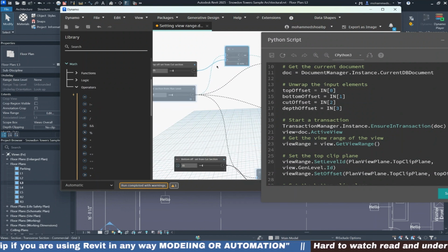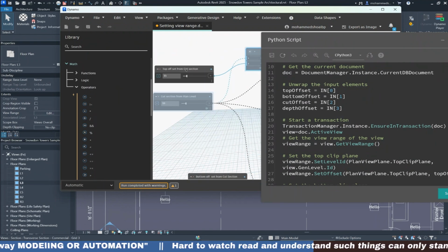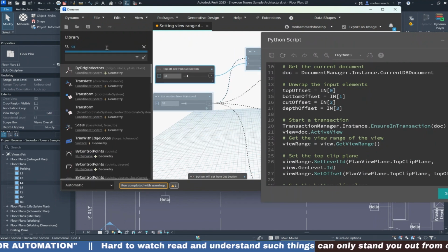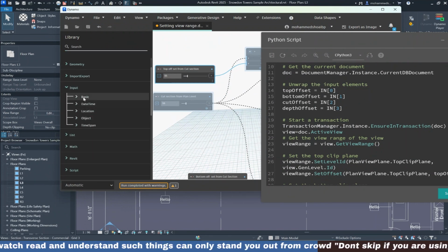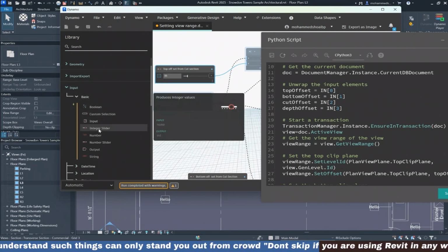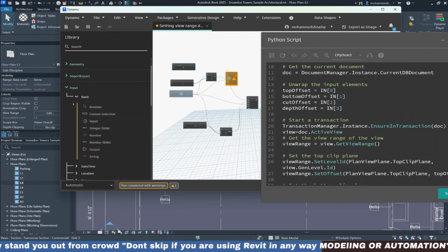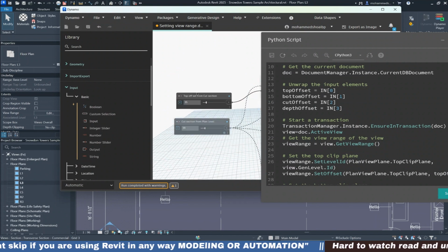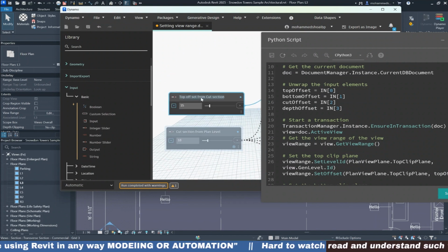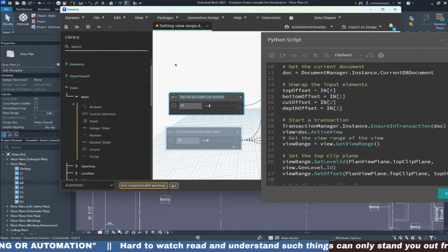In the add node, on the x input, select this and connect this slider. This is a slider. How to get this slider? We just have to type slider here, or you can go here in the input, basic input. Here you can get the integer slider. You can add this integer slider here. A slider node will directly come here. Okay, input slider. Here I change this node name by left clicking twice on the top of the node. You can change the name of the node.